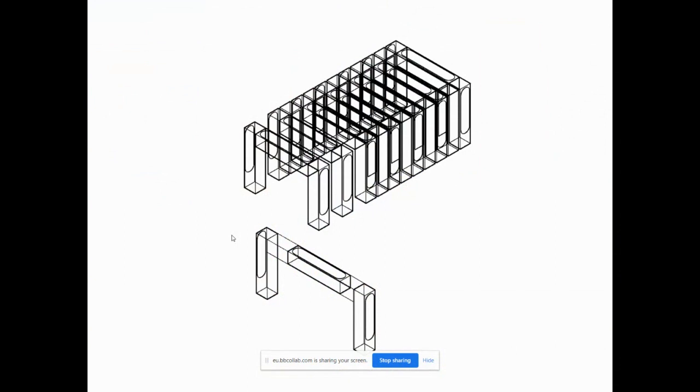So I said, well, we'll build this building like Stonehenge with just vaults with arches, and they'll be separated in the arches with a 300 mil gap, which we'll fill with concrete, because although the container is very strong, there are all sorts of fire problems with steel, as you know, and so the structure actually had to be concrete.